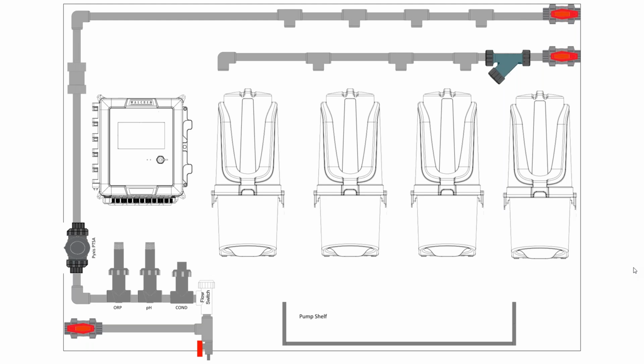Whenever you do any sort of recalibration on any sensor, you always look at the raw value first. Don't just go in there and assume that the value you're seeing should be altered with some sort of calibration, or you, the human being, forcing in a calibration. Look at your raw value. It should be within 15 to 20% of the actual. You should only be using calibration to tweak in a value. And if it's more than 15 to 20% off your raw value, then you have some decisions to make about troubleshooting. That's just the rule. And when everybody starts following that rule, we'll have a lot more successes.